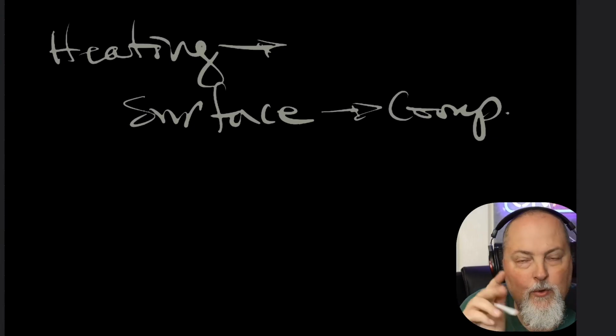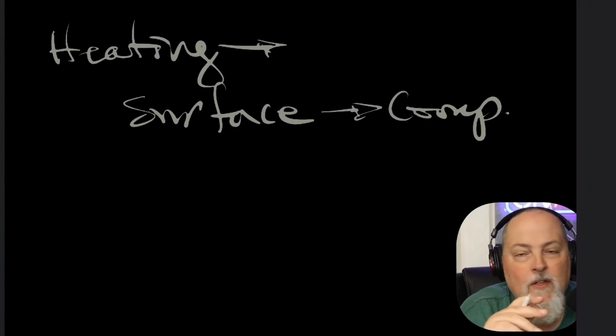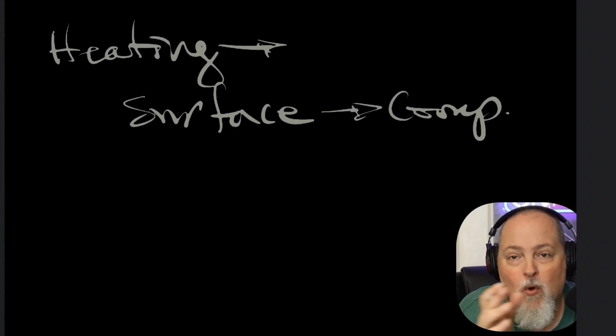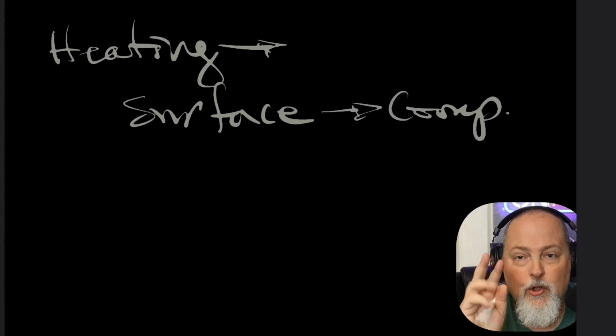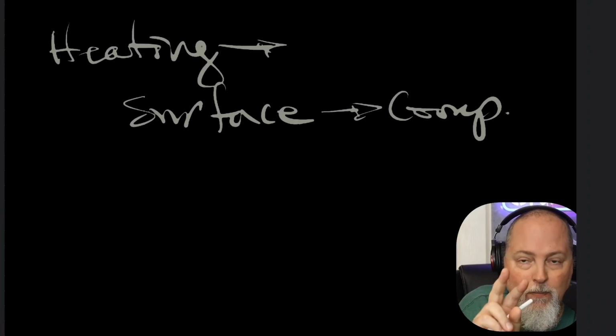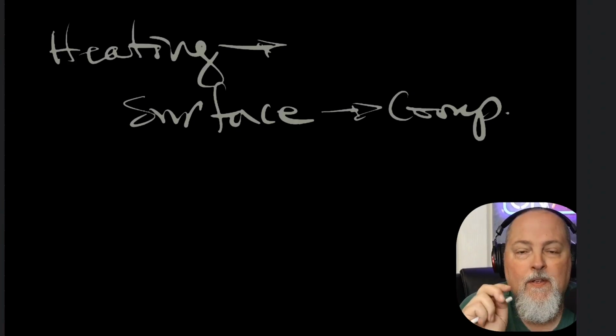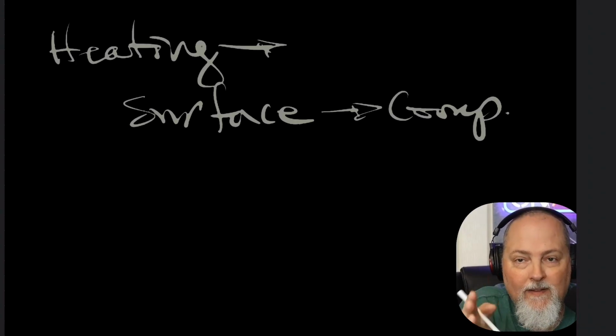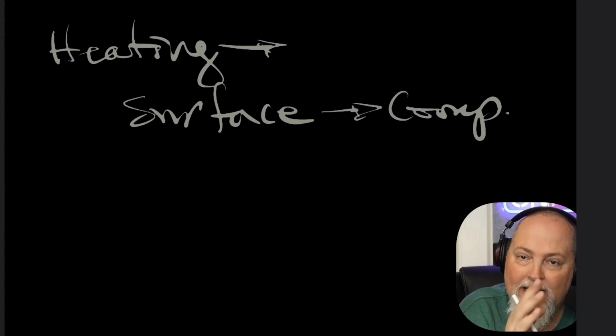We had two things we talked about in heating: tension and compression. So just know, no matter what, whether you're heating or cooling, you're only dealing with those two components, tension and compression. So when we're heating, the surface that's being heated is in compression and the interior is in tension. That tension is that resistance to the change.